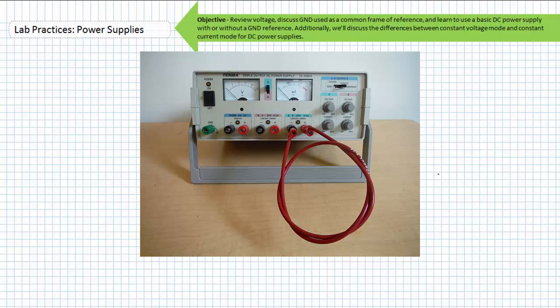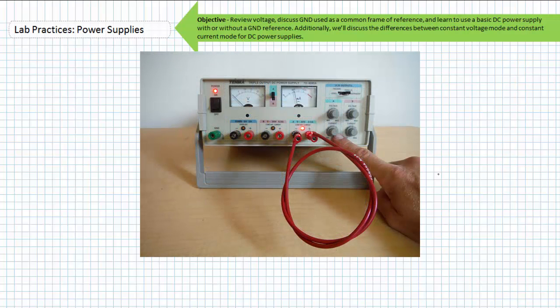Yes, this is a complete circuit, but it is a circuit of such extremely low resistance that we would ordinarily expect a constant voltage power supply to deliver extremely high, dangerous current because the resistance is so low. Obviously, I'm intending this circuit to demonstrate the constant current mode of our power supply. In the face of such a heinously wrong event, even if I had the power supply set to 20.78 volts, the power supply instantly pegs at the maximum current, in this case around 200 milliamperes.